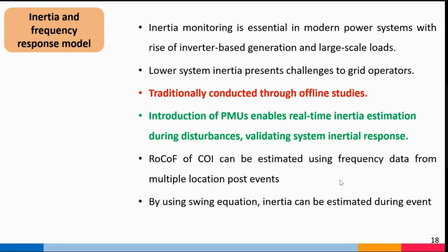To overcome those inertia challenges, they are going for installation of synchronous condensers, which provide fault level as well as inertial support to the system, also by utilizing external flywheels. That's why inertia monitoring is very important.